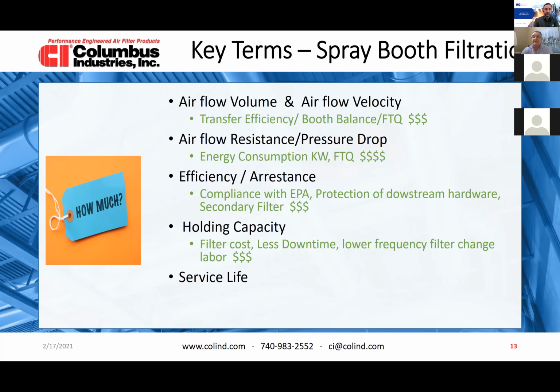Holding capacity, when we talked about this, what is the cost effect of holding capacity? Of course, first of all, filter cost, because you're not changing it as often, and then less downtime to change filters, lower frequency of filter changes, so your labor costs will be lower, not to mention other factors like stock, transport, and all of that stuff. So the spray booth ownership cost altogether is lower when you have higher holding capacity filtration.